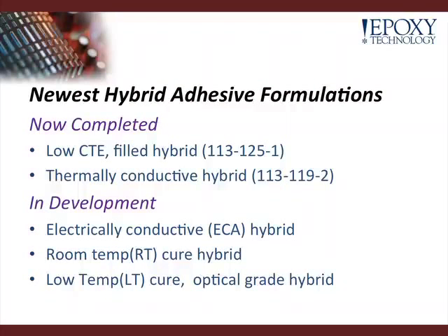Onto the roadmap for our UV hybrid systems. So we've just recently completed a low CTE filled hybrid. Additionally, we now have a thermally conductive hybrid. These are both filled systems that are UV tackable and thermally post-curable.